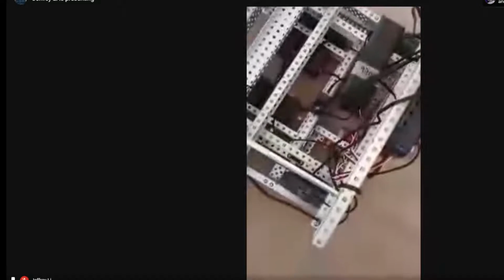If I have the controller right here, this is pretty cool, right? My inputs are 0. Before that, this is what I meant by the actuation points. Before, the only thing we could control a robot through were the actuators and the voltages on the motors, which meant all we were telling it was to go 0 voltage. Now, the way our code is interpreted, the robot thinks it's being told to go 0 speed, right? And 0 speed is not the same thing as 0 voltage.